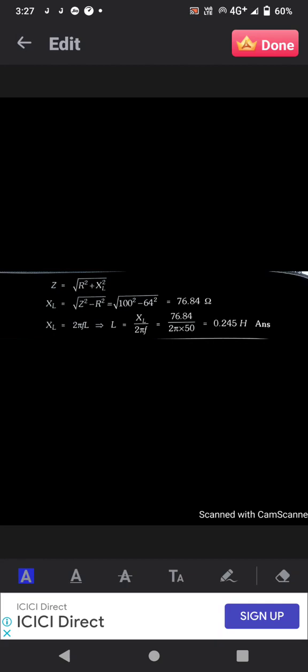XL equals 2 pi FL. The inductive reactance formula is XL equal to 2 pi FL. From that, XL divided by 2 pi F gives the inductance. Like that we can calculate the resistance value and the inductance value. This is the second problem.